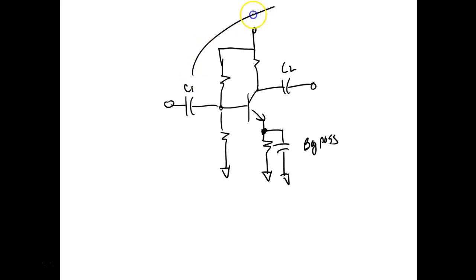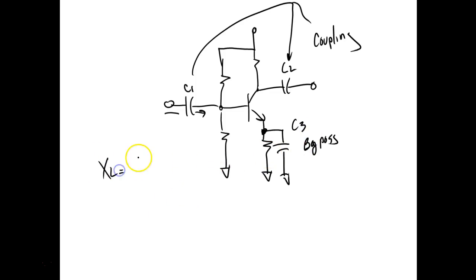What do we call these? These are called coupling capacitors, because what they do is they allow us to couple the AC into a DC circuit, right? You understand? So these are called coupling capacitors. So these guys right here, if I call this C3 down here, these guys set the low frequency right there, because how much opposition they give is 1 over 2 pi FL.